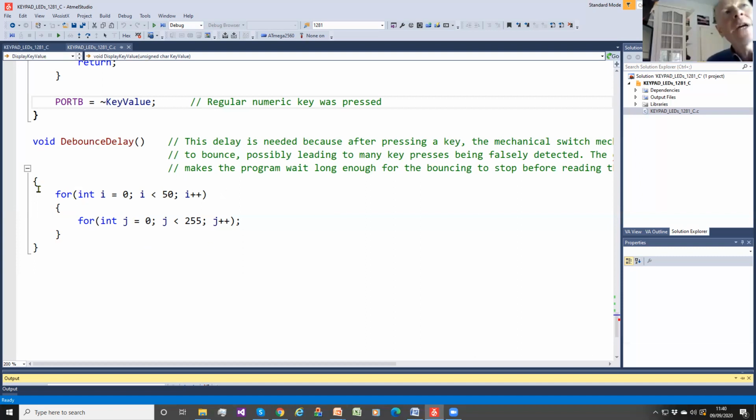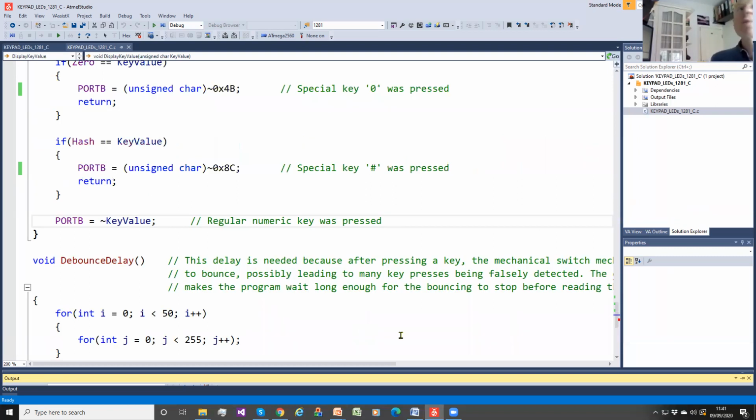this short loop here is basically saying, for a keyboard switch, normally between 20 and 100 milliseconds is the most it will be doing that for. So when I've detected the key the first time, ignore the next set of bounces. That's all that is really doing. If you don't do that, you get weird output, especially with keypads, but strictly speaking, you might have to do it with other types of switch as well, but especially with keypad type switches, you must do this, okay? Because of the way they work.